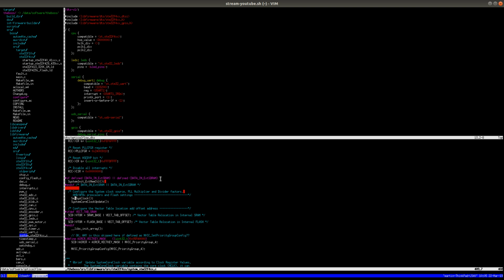So when FreeRTOS starts running from the internal oscillator, it could actually misconfigure the system core clock or the SysTick, the system tick clock, which is used to schedule tasks. So things like thread sleep may not work correctly, and that's something I would have to check after I make those changes, to make sure that everything continues to run properly after the clocks are configured and the chip switches to the full speed PLL clock, which in this case should be able to run at 100 megahertz.